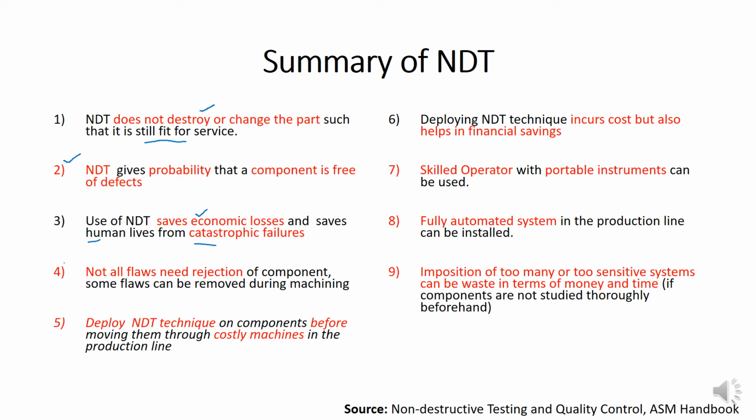So not all flaws need rejection of the components, because some surface flaws can be removed during machining. This is just an example: if there is any surface flaw, during machining that can be easily removed. So we have to take this into consideration as well.